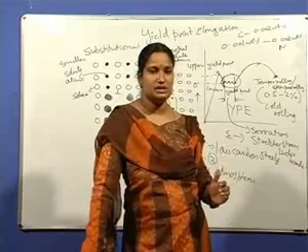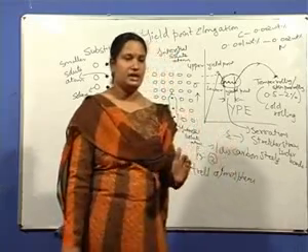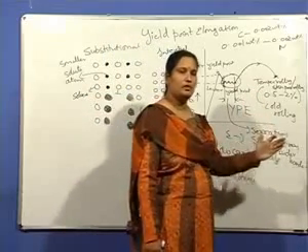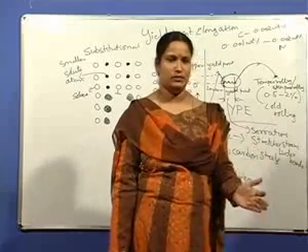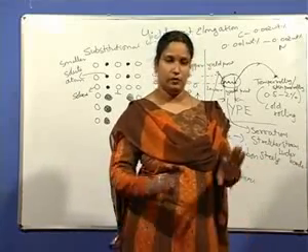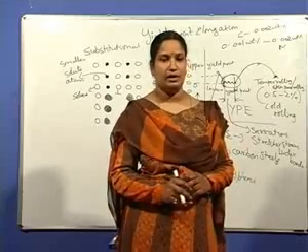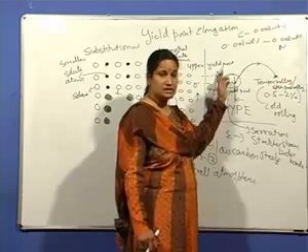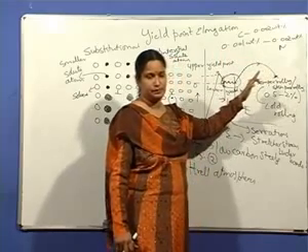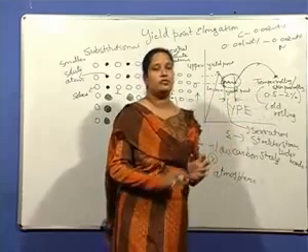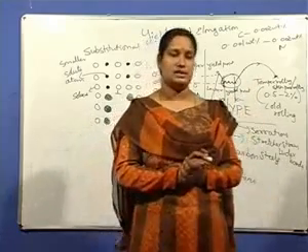Strain aging means, if the material is left after temper rolling and skin pass rolling, and is not immediately formed, if it is left at room temperature for a few days and you try to form it, the yield point is slightly increased, and the reappearance of the yield point phenomenon is seen.